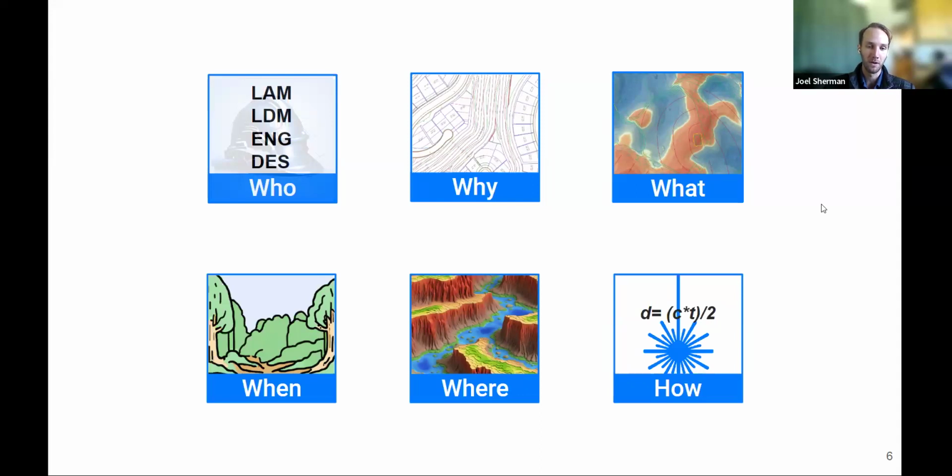So yeah, really highly recommended on areas where there's moderate to significant topographic changes, and when there are any obscuring vegetative structures or structures in general that prevent being able to measure the site well using normal photogrammetry workflows. LiDAR is where that steps in and it really shines and allows you to derive these original grade data sets. There's plenty on where, so how.